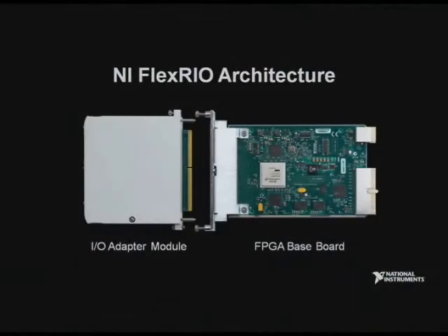So the FlexRIO architecture consists of a programmable FPGA device coupled with interchangeable I/O adapter modules. Now the adapter modules provide the application-specific I/O, analog or digital, that you require, while the FPGA module allows you to implement custom algorithms in hardware.